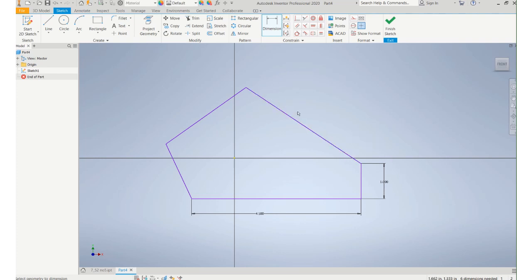Now this dimension's on an angle. When I go to dimension it, it's going to try to put a linear dimension, but I don't want a linear. I want an aligned dimension. So if you click that line the second time, then it'll line it up with the angle. Let's see, this one here is also an aligned dimension, so I'll click that the second time, put in the